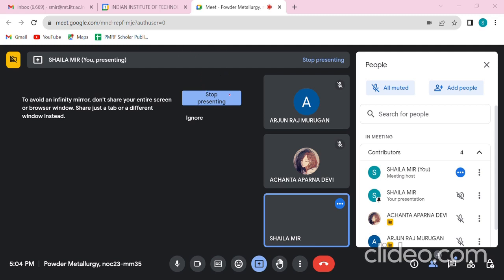Basically, the sintering process is that after compacting the mold, we have the compacted mass of a material, and then we are trying to sinter it. Post compaction, there are certain pores present inside this compact. During the sintering process, because we are trying to decrease the porosity of the material, the pores will try to be annihilated, and then we have a higher density of the material.